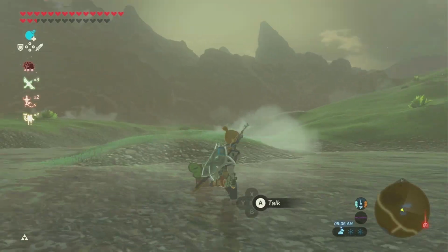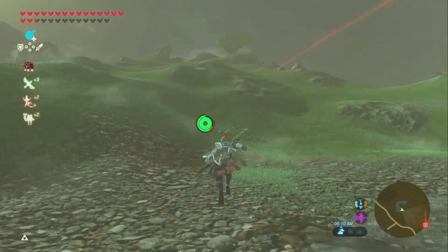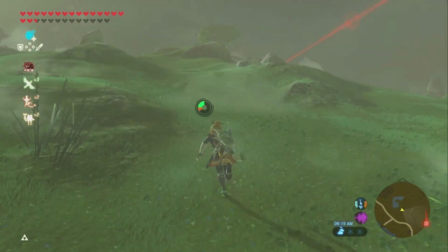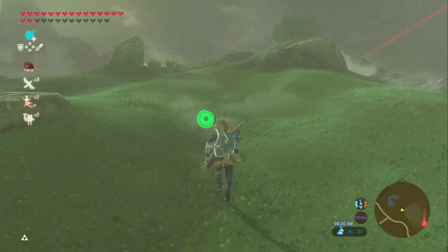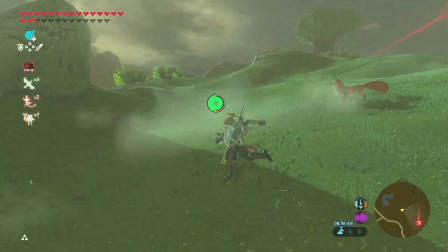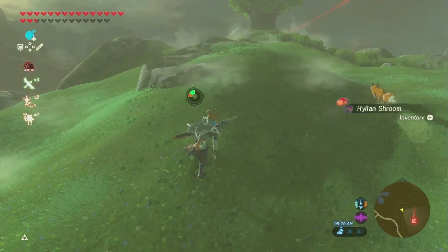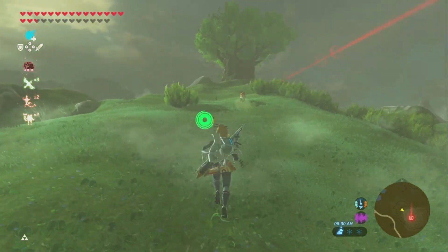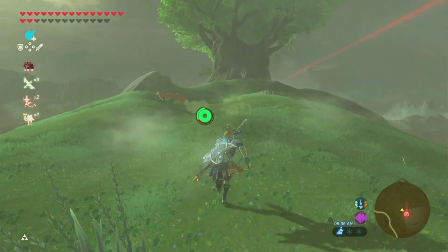Low pressure and flow on just the hot water plumbing is fairly common. Where the piping is galvanized steel, you can expect the rust to be heavier on the hot water piping, and the low water pressure on the hot side is not a surprise. The hot water piping arrangement is usually larger than the cold water, so slightly lower pressure may be expected.